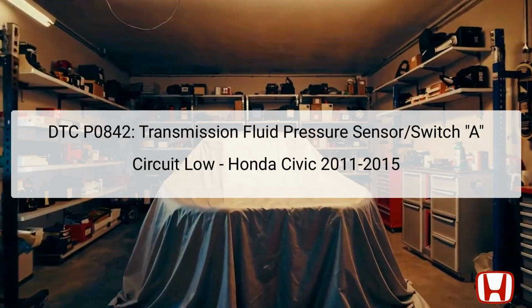DTC P0842 signifies an issue within the transmission fluid pressure sensor or its circuit, specifically indicating that the pressure sensor or switch A is detecting a low voltage condition. This diagnostic trouble code affects the CVT, continuously variable transmission, of the Honda Civic models from 2011 to 2015.